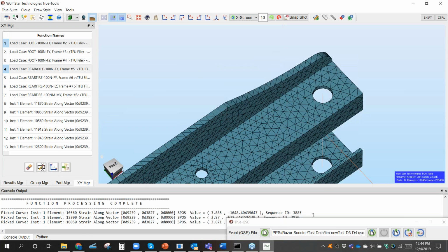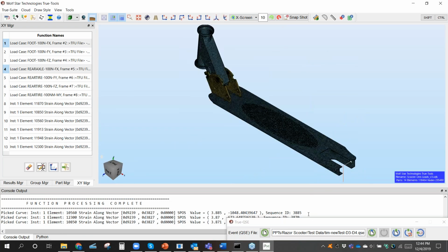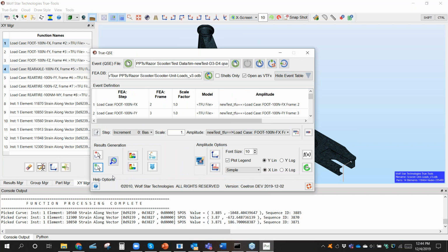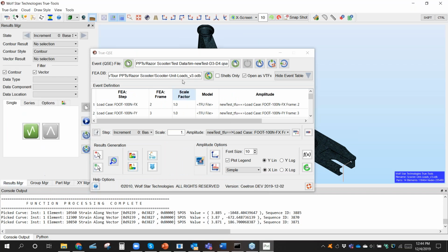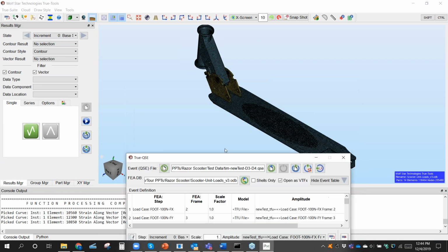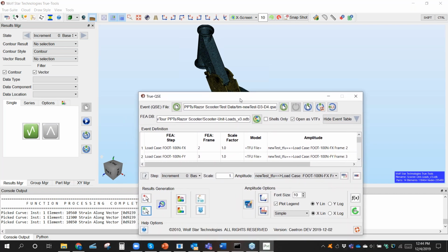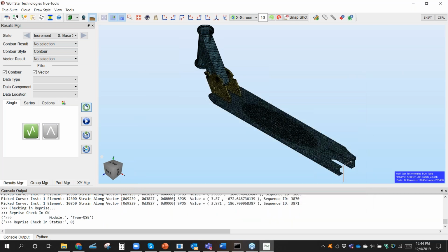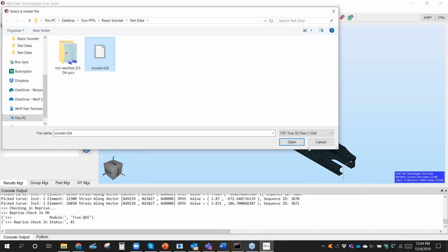And so what we can also do now is we can go in and calculate an operating deflection shape or go off to FE safe. It'll take a few minutes to calculate the operating deflection shape on the structure. I've already run that, so I'm just going to pull that up real quickly, and I'll show you the operating deflection shape. Okay, so I'm just going to put this away. I'm going to open up my operating deflection shape file.